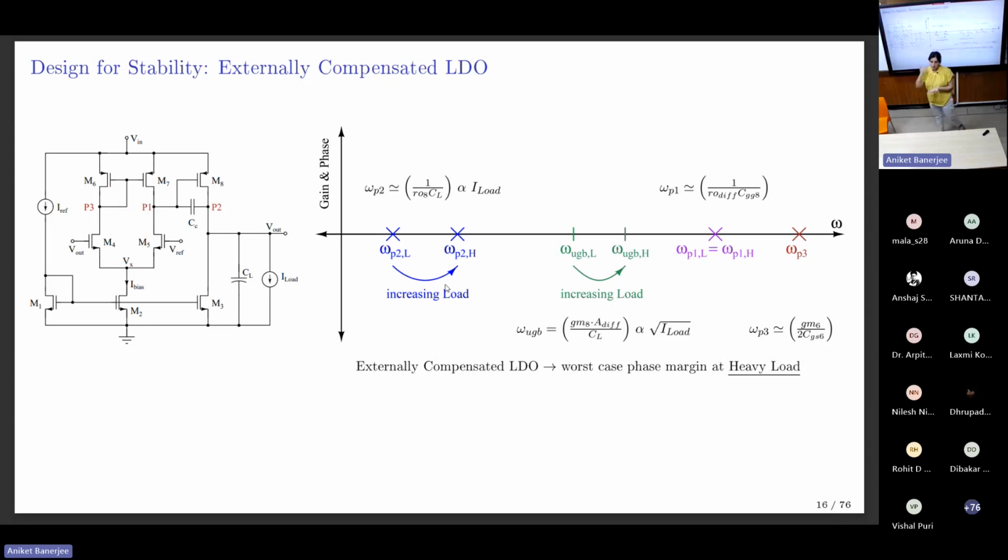The specific thing about an LDO is I'm drawing a certain load, right? So when I'm drawing the load, circuit parameters would change, like gm would change, gain would change. So all the stability analysis, the pole-zero analysis that you do, will keep moving with respect to load current. And I need to know that to establish, if it is monotonic in nature, the worst case in order to design a workflow for it.